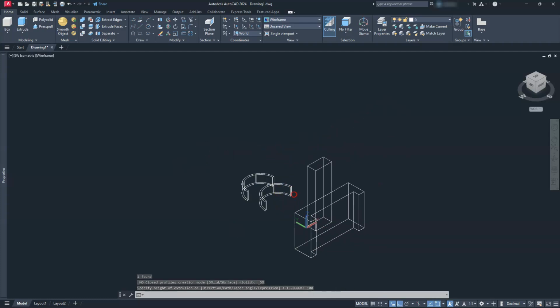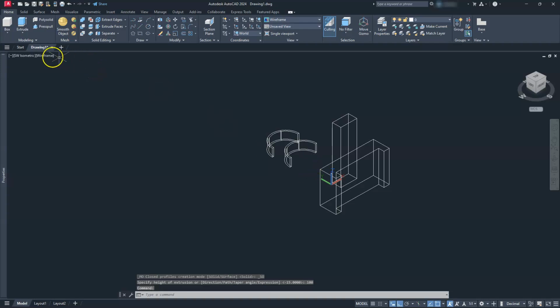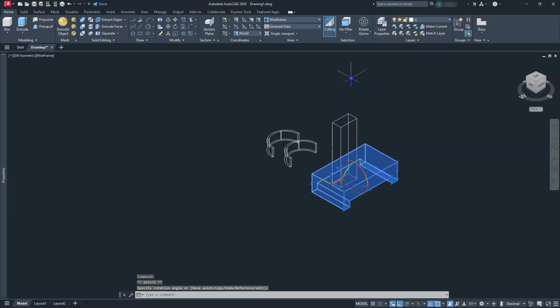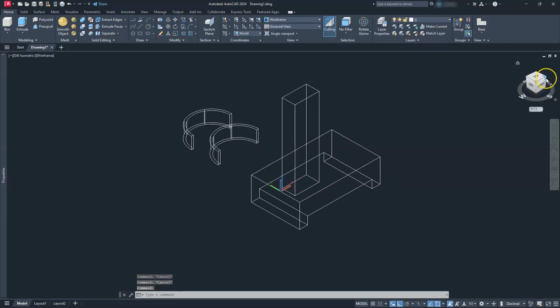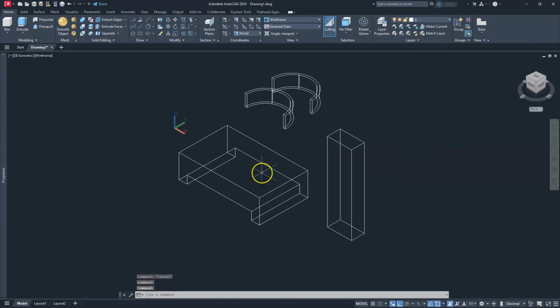All right, so this is all I need to create my shape here. Now I do have it in wireframe, so I can take advantage of my gizmo. So I'll go to the rotate gizmo. I'll go ahead and select this shape. I'll select the red axis here and I'm just going to stand this shape going up in that direction, right? Now I always like to keep an eye on which way is my front view. So let me rotate this around to where I can see that the front is going this way. This is the right side and this is the top. I try to keep it as closely resembling what my drawing is if I know that, or the most detailed part of my drawing should be the front view.